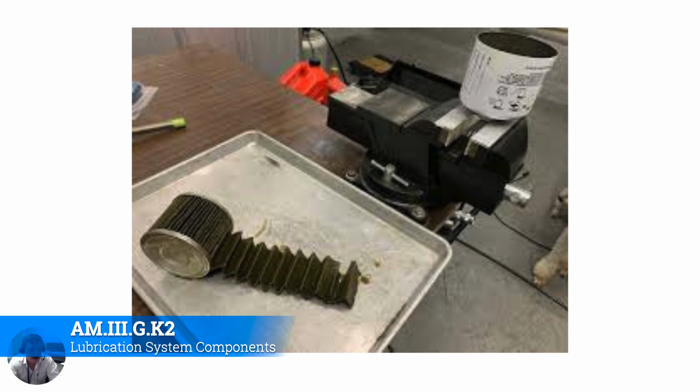Even though it may be painful and expensive to fix an engine like that, it's better to do that than find out about the engine eating itself at 4,000 feet in the air. But yeah, that's an engine oil filter. Not really that different. You have an engine screen, and then the filter itself, and the filter you have to break apart. Other than that, it's pretty much like a car.